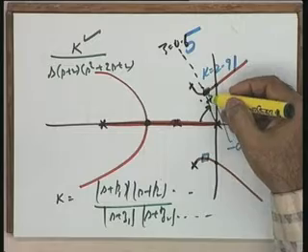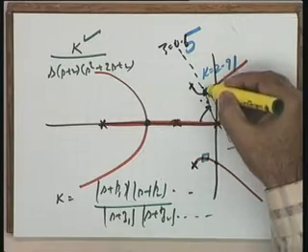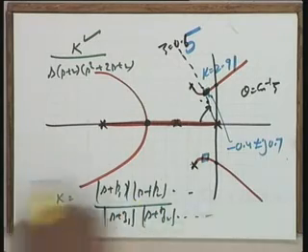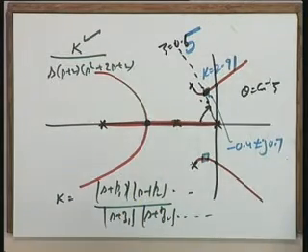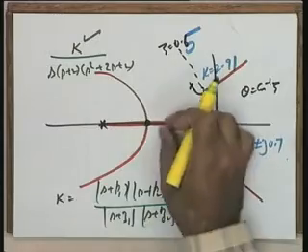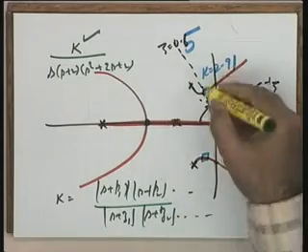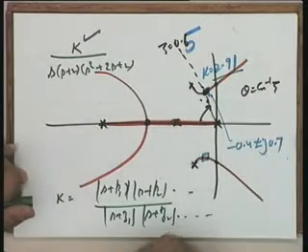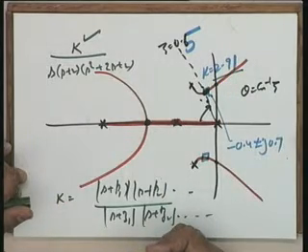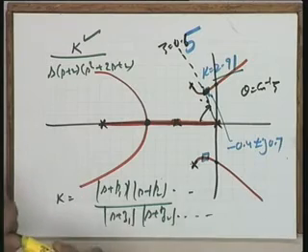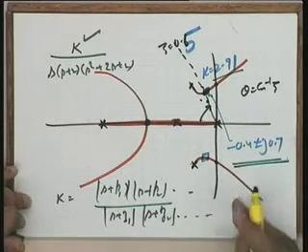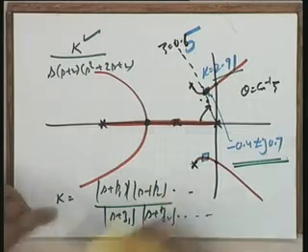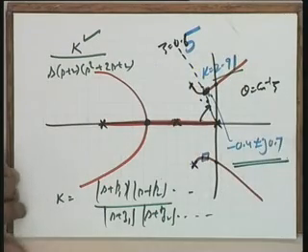So, graphically a quick answer can be obtained by taking this value into this value into this value into this value. Since there is no zero here, the denominator will not have any value. So, the denominator is 1. Otherwise, in the denominator the corresponding magnitudes would have come. So, the value of k can be calculated over here, and as per the notes here, the value of k turns out to be 2.91. Okay. So, the value of k is 2.91, and the corresponding closed loop poles are minus 0.4 plus minus j 0.7. Now, this corresponds to the value of zeta equal to 0.5.